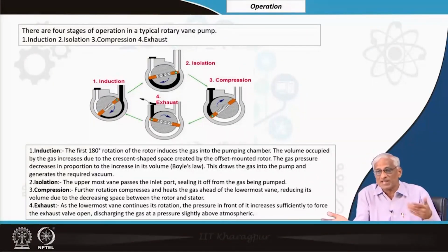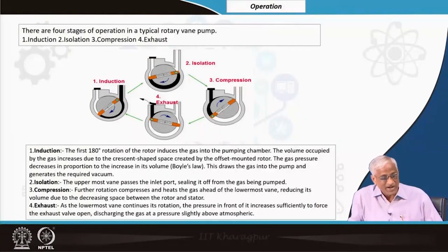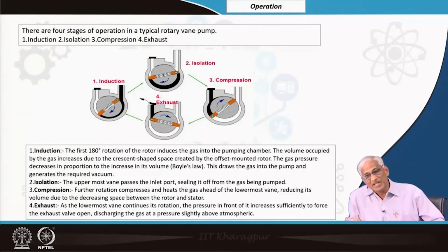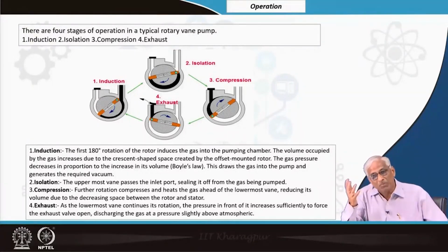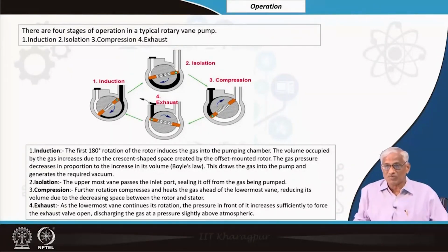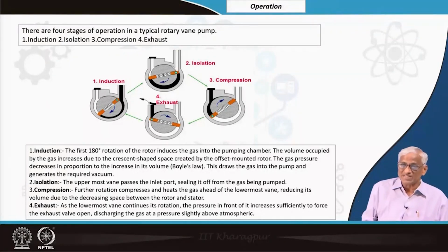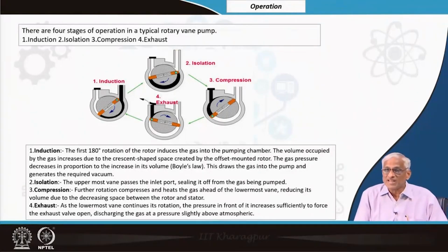That is called 2 stages connected in series. Then you will get better vacuum. But there again another pressure level, another vacuum level will come, it cannot be more than that. Again the exhaust valve will stop. So, again the pumping action ceases. So, you cannot create 3 stages, because at some stage the oil that is being used as a lubricant itself will produce some vapors.